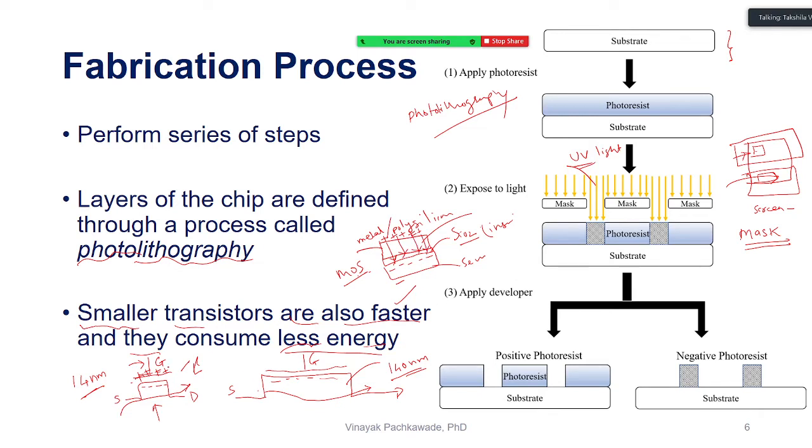So what I am saying is that a smaller transistor will need less energy because they are so power efficient. They just need little energy for their operation. It means I am needing only a few charge carriers here to charge the gate and to make the transistor work, as compared to this technology. I will need a large number of charge carriers. It means I will need a larger electric field. Obviously it is related with the energy.